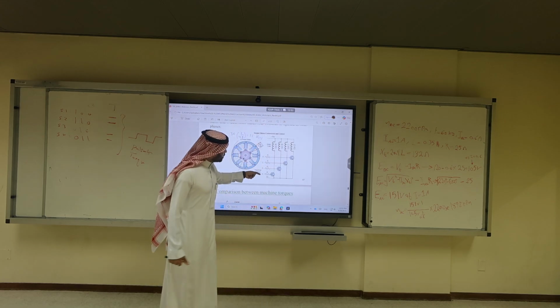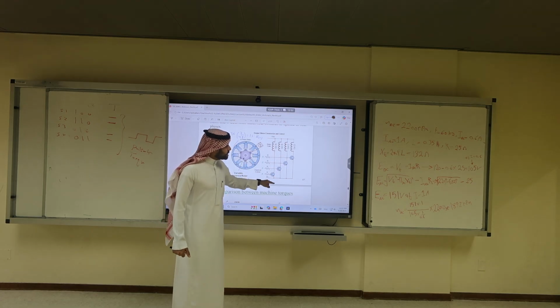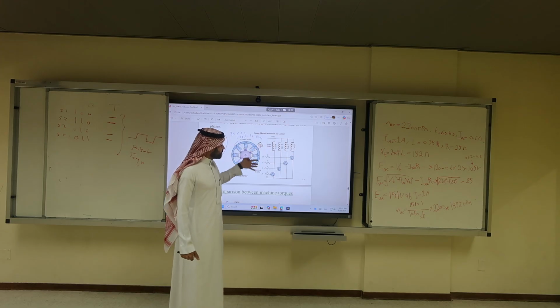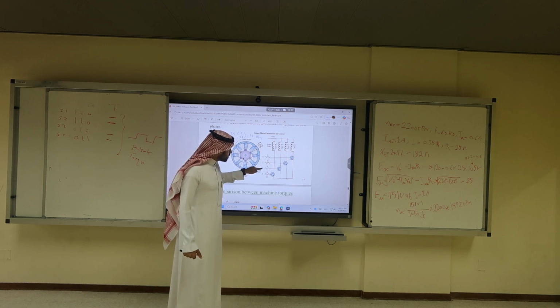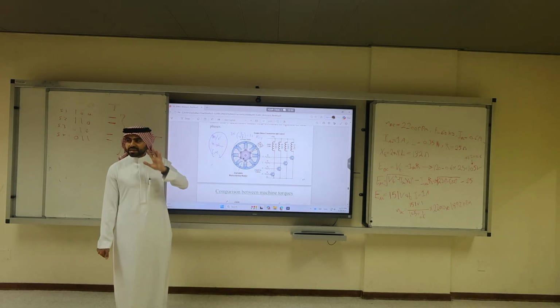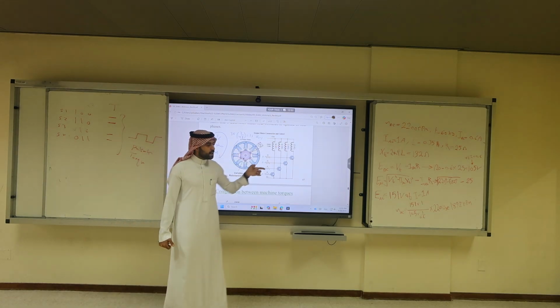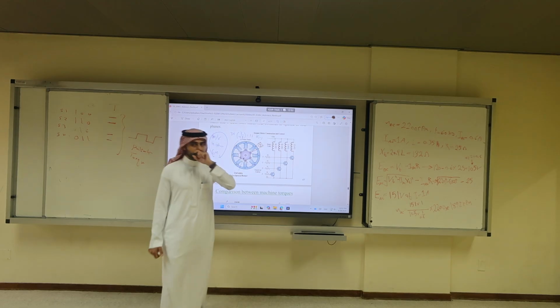What will happen is you connect all the phases through a resistor for protection to IGBTs or MOSFETs, whatever you choose. And then you connect each one of the coils to the supply. And here you send your pulses, A, B, C, D. So these are the 4 phases, but you send 4 control signals, one for every phase. All of them are DC. This is not 3-phase AC. Any phase is a coil. There's a coil, there's a coil, there's a coil. And you send the 4 control signals, 1 0 0, 1 0 1, through this power electronics.